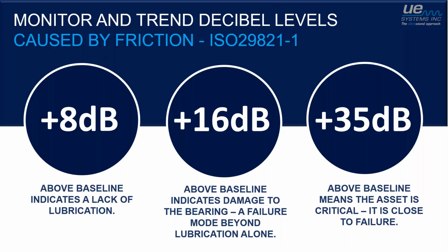And with the way ultrasound works, this is documented in an ISO standard, right? So this isn't something we've pulled out of the air. Everything is based off a baseline. What is our ideal friction? Getting that ideal friction is a little challenging, because often when we start to use ultrasound, we're not on a perfectly packed, well-installed bearing. The bearing's been out there spinning in a circle for a lot of hours, or in some cases years, right? So you don't know if it's in that sweet spot that Mark was talking about. I'll address that a little further in terms of how to set the baseline.